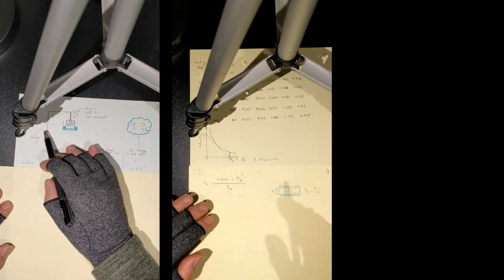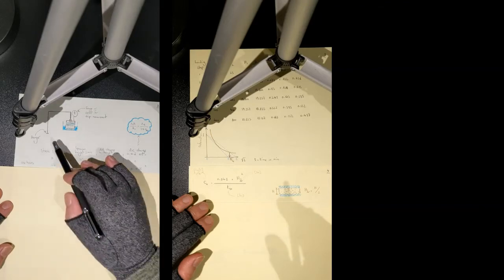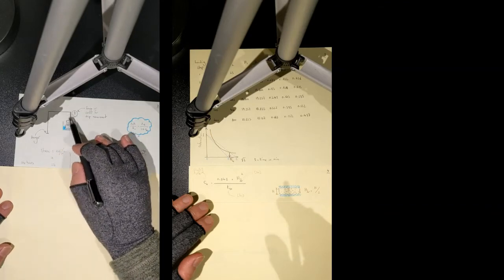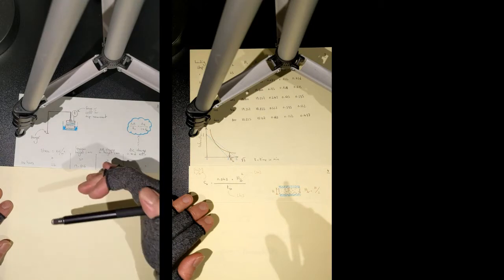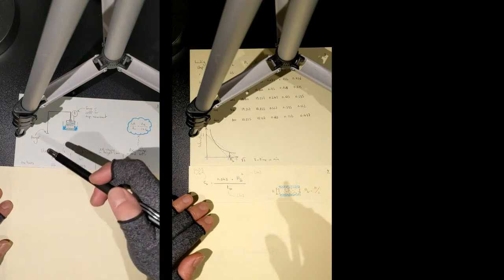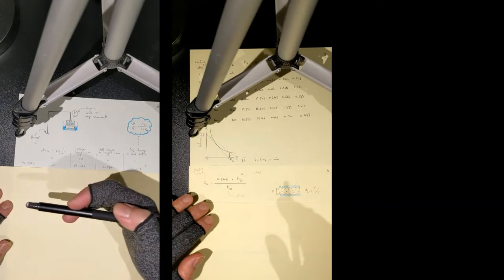So at the beginning of the test, the stress on your soil sample is 0, the dial gauge is showing 0, everything is 0, and the specimen height is the original height, 20 millimeters. Then you add your first dead weight on the hanger to apply the first stage of loading on your soil specimen. You will keep the soil specimen under that initial load for 24 hours.